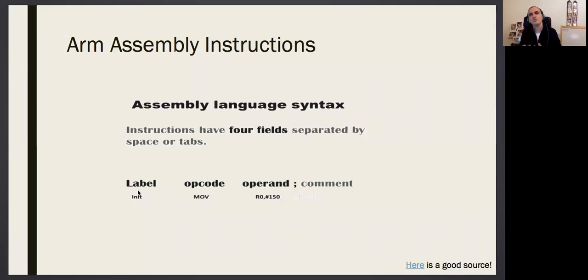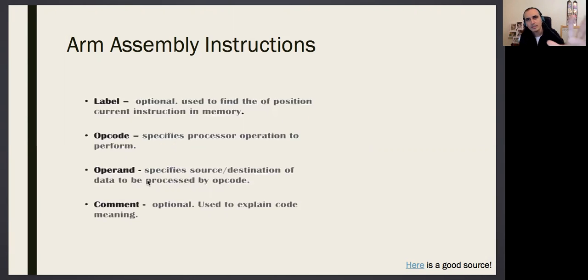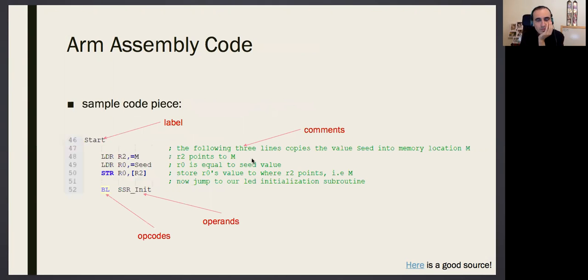But we are not going to write the memory address like 001, because an address in a memory is a hexadecimal or binary number. Instead, we'll be using labels. We'll say start, and we'll understand that code starting from that point will be written to a part of the instruction memory, and we are pointing to that memory by saying start. Whenever you say start, it will be pointing to that part. How? You'll get there.